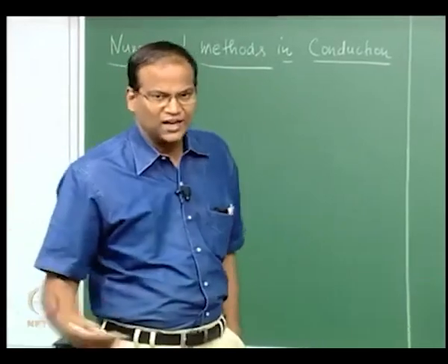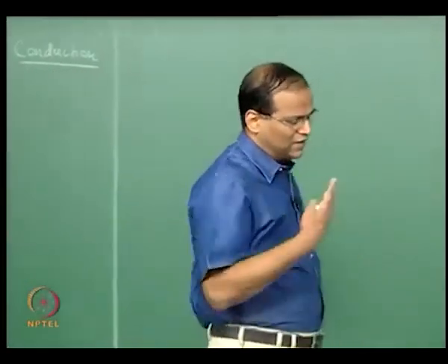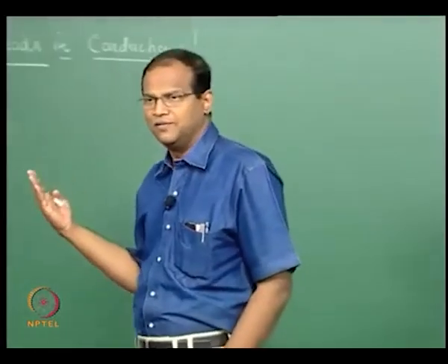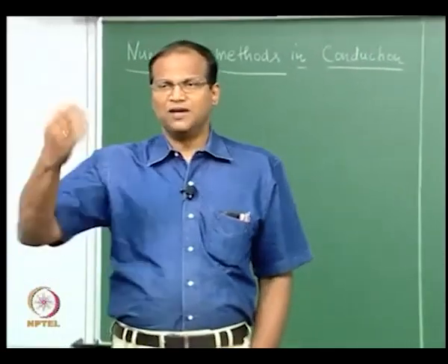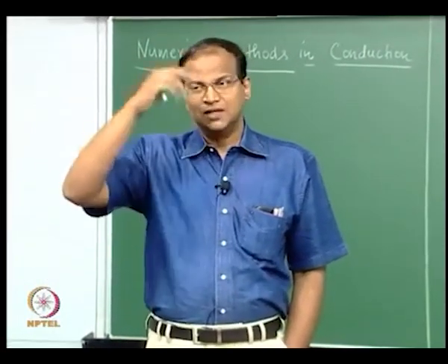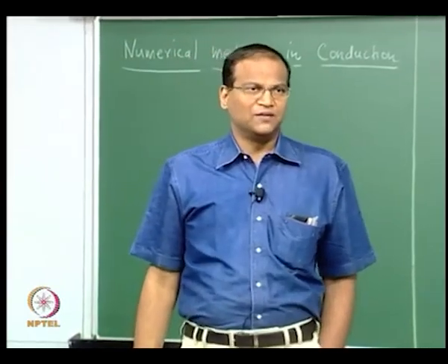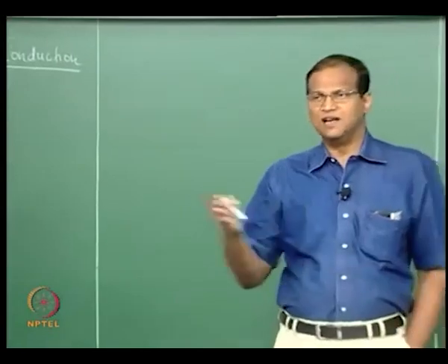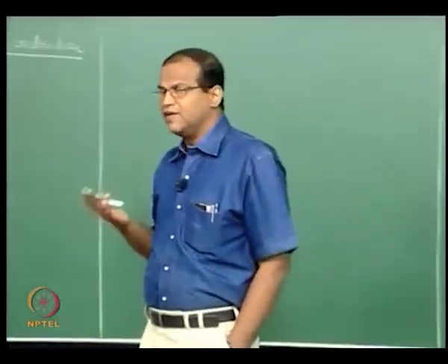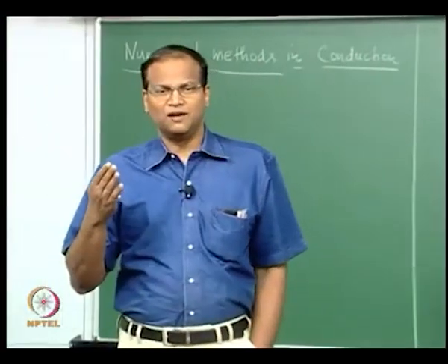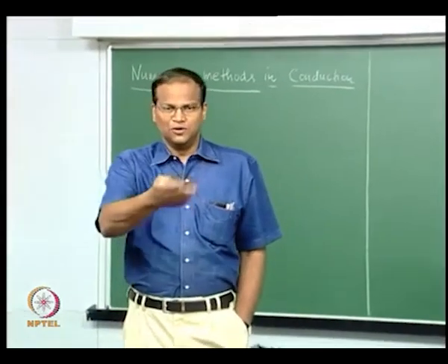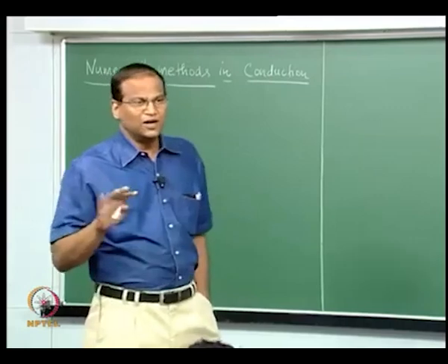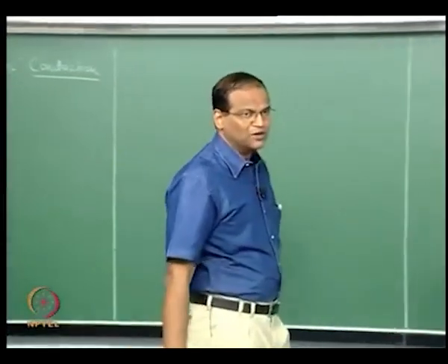So these lambdas are called eigenvalues of the problem, and then finally you got a solution in terms of sin n pi x by L and sinh n pi y by L. The sinh n pi y by L in yesterday's class was basically because the temperature was exponentially decaying in the y direction. As far as the sin n pi x by L is concerned, it is basically a periodic boundary condition. In fact, it is because of this sin n pi x by L that you are able to invoke the orthogonality property. That is why this periodic boundary condition, the 0 boundary condition, is very important.